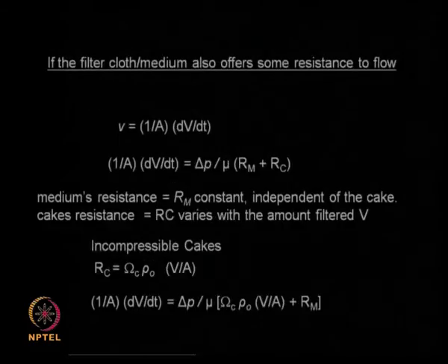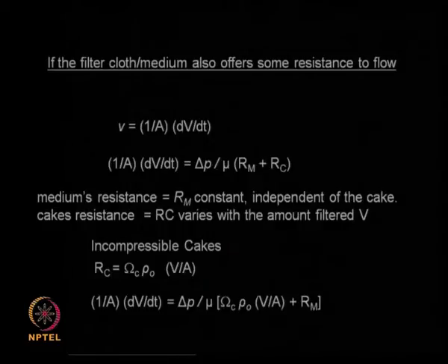Okay. So far we talked about the filter cloth or the filter medium not offering any resistance to the flow, but there could be some situations where the filter medium itself can be offering some resistance to the flow of the liquid. Generally if you design a filtration unit, you like to keep the resistance offered by the filter medium minimum, but there are situations where the filter medium itself can offer some resistance.